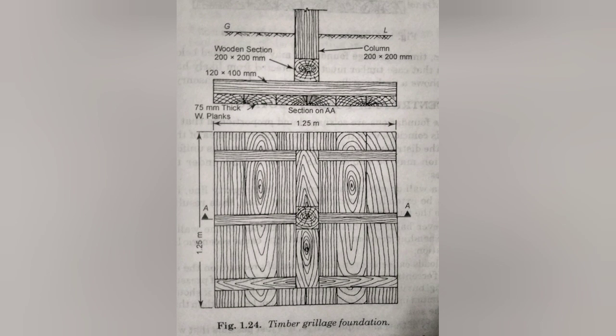Next is timber grillage foundation. Timber grillage foundation using timber planks and timber beams can also be used to support heavy loads on poor soil, but such a foundation should be adopted when the soil where it is to be constructed always remains waterlogged. In this foundation, no concrete block is used, but instead a